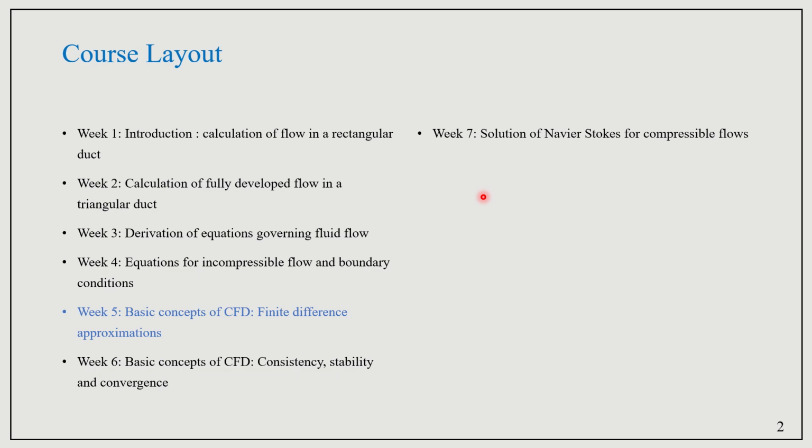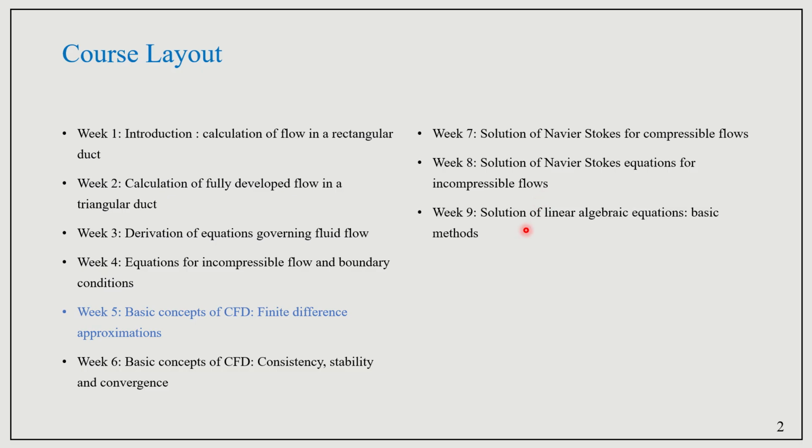To know that, we need to know how to solve Navier-Stokes equations, because those are a coupled system of equations. It is not very easy to solve those equations. So, solution of Navier-Stokes for compressible flows as well as incompressible flows. And finally it is about the solution of linear algebraic equations, because we are converting the partial differential equations into linear algebraic equations by using discretization schemes like finite difference, finite volume or finite element approaches, which we will not be mostly dealing with. But we are converting PDEs into linear algebraic equations, and we must know the numerical techniques to solve those equations.